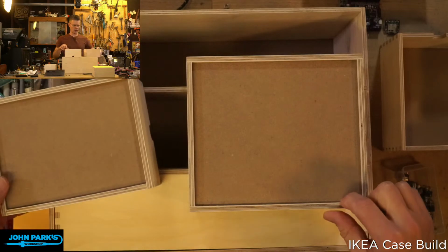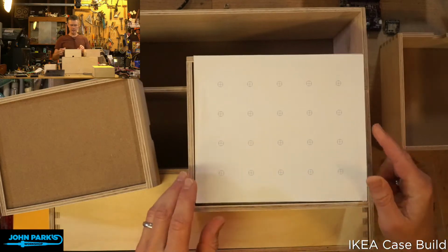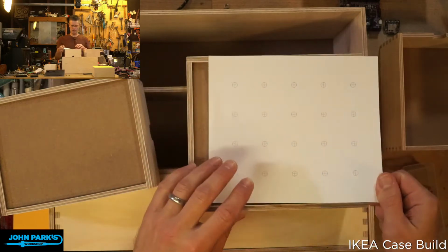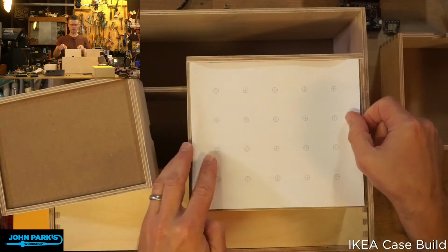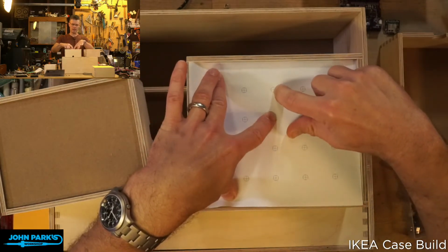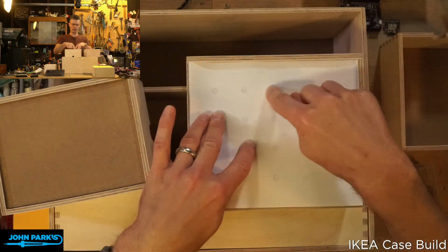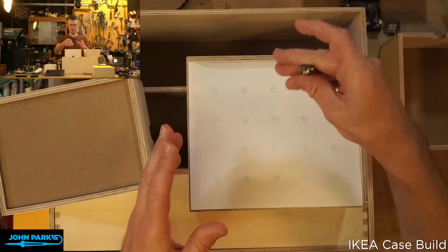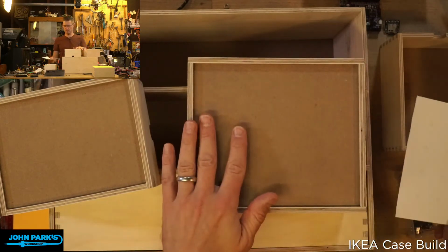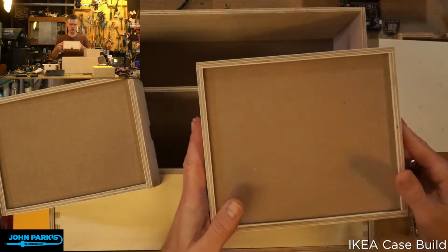And what I did was I went ahead and made an array of circles with some center guides. I need to cut that a little smaller so that it fits precisely. What you could do is just tape that down and go ahead and tap a little starter point or pilot hole and then drill those out carefully. And off you go, and then maybe you could add your paper template or paint it, mask this and paint it. I went an extra step with that and used the laser cutter to cut that out.